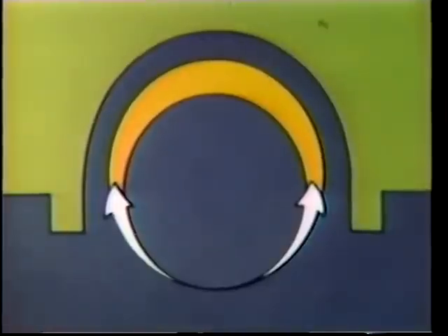When this happens, the bearing and shaft are in metal-to-metal contact. When the shaft begins to roll, its motion drags oil underneath it. Oil sticks to the shaft as it turns and is carried between the two surfaces. The shaft is lifted away from the surface of the bearing by a film of oil.